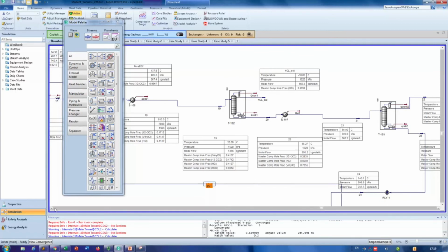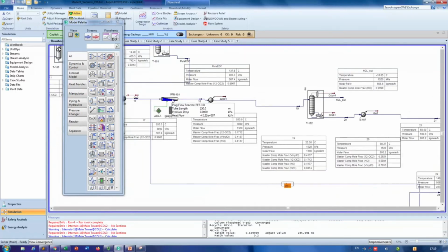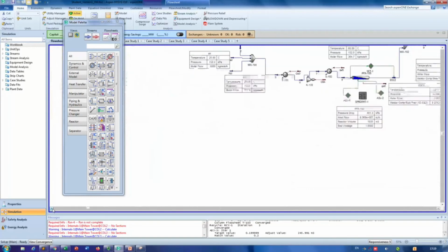So we take the product from, look at the big process flow sheet. We pyrolyze, and then we take hydrochloric acid. We are going to take this HCl out, and then feed it back to the oxychlorination reaction, which is here, and then we can delete this particular stream.